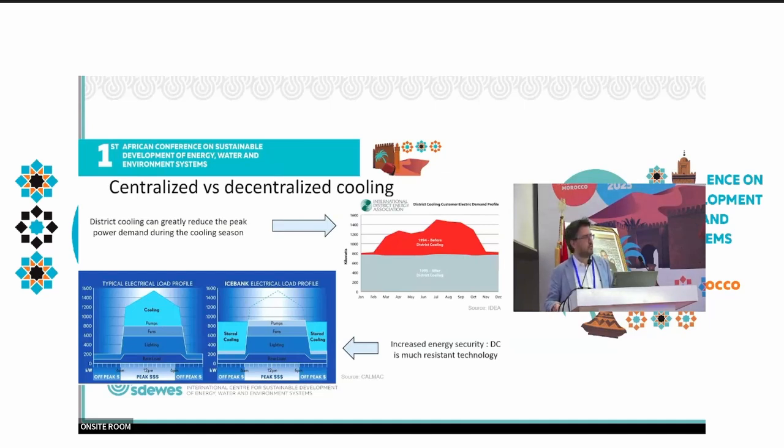Euroheat and Power, I suppose some of you that work in district heating or cooling have probably heard about them. They had a big policy paper where they calculated that utilizing district cooling in Europe in the long run can reduce the need for around 50 gigawatts of electrical capacity, which accounts for around 30 billion euros in capacity and infrastructure. And they calculated that with this 30 billion euros, you can cover almost 50% of the cost of the new district cooling systems that could replace them.